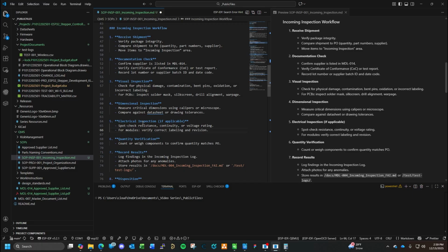We're going to spot check, and we'll run through the process when we're actually checking these boards and doing our incoming inspection. So with a PCB, I'll use a multimeter and make sure we don't have any direct shorts between ground and 3 volts and 5 volts. We'll make sure there's actually no shorts that exist in the board, because that's your first critical failure, if you have a PCB that's manufactured wrong and you have a direct short. That does happen. That's why I did the Gerber review, to make sure the artwork was correct.